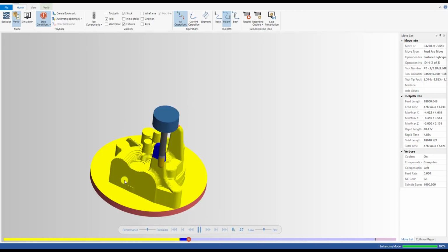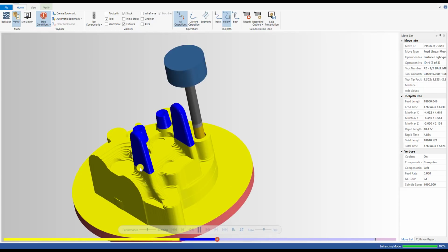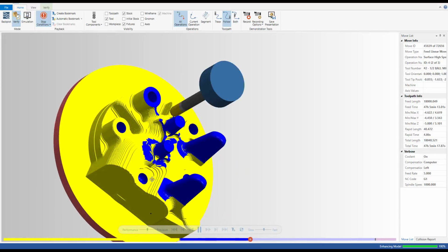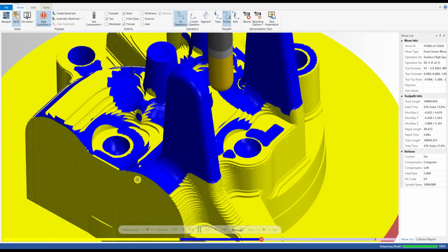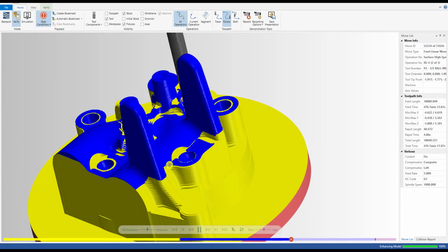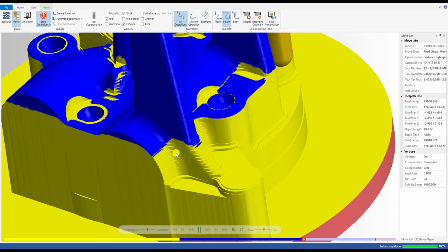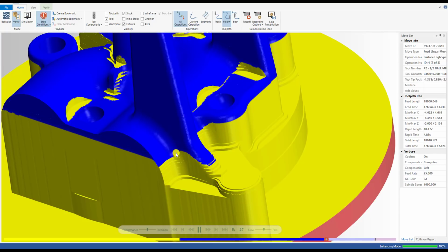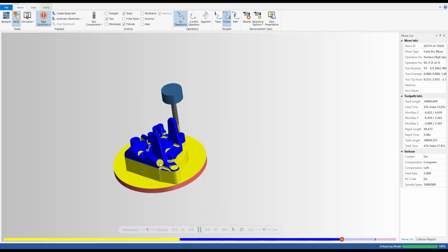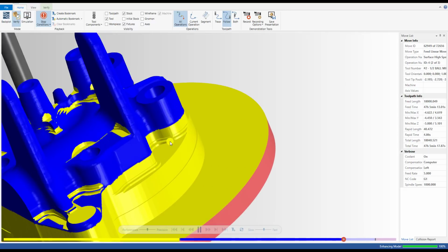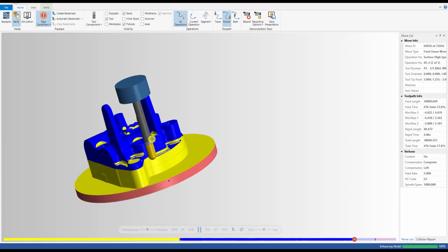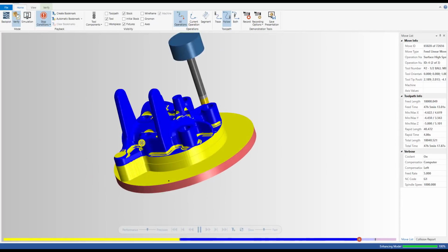And this is the finished Toolpath. This is the hybrid. Oh, this tool goes into the hole also. You see on the vertical corner here, there's no problem because we use, I think, a half inch end mill, so it has the same radius as the finish tool on the vertical fillet. But on the horizontal fillet here, we have a difference in the radius of the tool in the horizontal direction. So that's what we have. Yeah, we have the same problem.